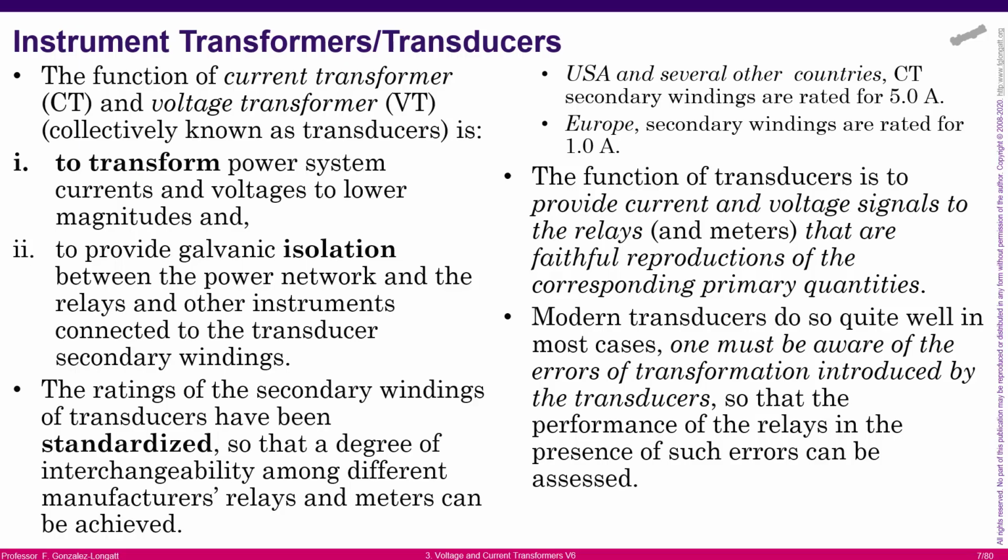Okay, well, let's go to the main discussion about instrument transformers, also called transducers. What is the idea of those kinds of devices? Well, in power systems, usually at substation level, we work with very big voltages and currents. I mean kilovolts and kiloamps. However, relays, power system protections, and some monitoring systems all work with very low voltages and very low currents.